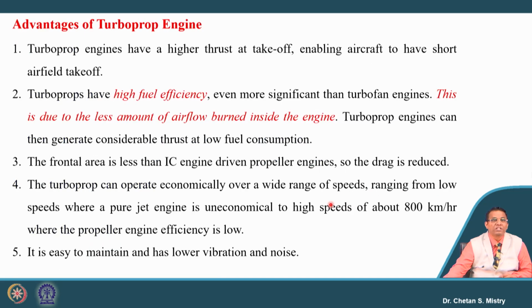Now let's discuss what are the advantages of the turboprop engine, and that's the reason why it has been applied for aircraft also. So what are the benefits? It generates very high takeoff thrust, and that's the reason why a short takeoff length is required. So most of the regional transport aircraft you are looking at are with turboprop engines.